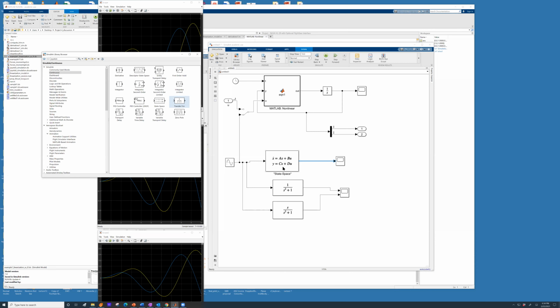Okay, at this point, I just want to make sure that everyone understood what we did here. And I'm sorry I did not go back and forth, because I'll tell you what happens if you go back and forth. If you go back and forth, one plot, two inputs in the scope. Yeah, because the scope is grabbing output from first equation and output from second equation. So this is the plot of output. If you want input versus output plot, then you need to create XY plot.